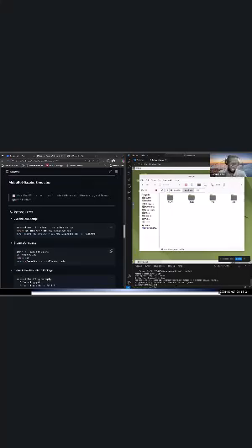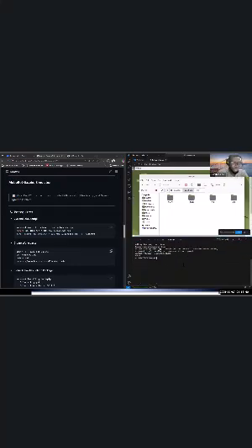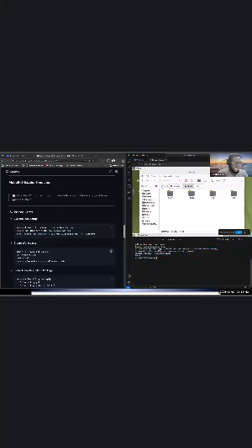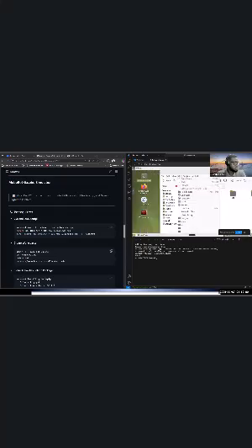let's see. Control Shift V. Should show Humble. Perfect. Can we all see Humble? If you have this output, it means you've installed ROS properly. I'll drop it in the chat. Okay, now we'll go to the next step. This is just to show that we are good and ROS is installed on this computer, in this virtual environment. You can see that I'm running another operating system in VS Code. I can do this because of the extension I installed on VS Code.